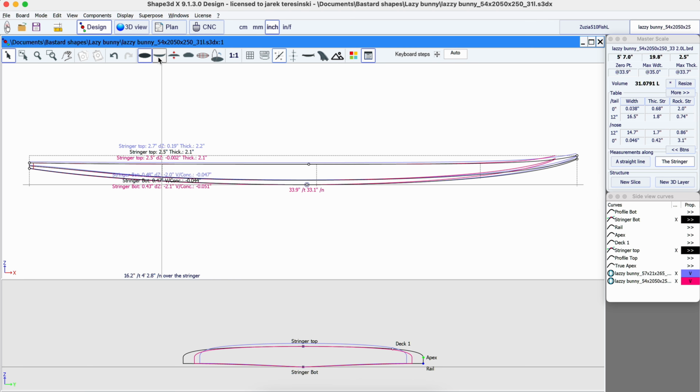Things about the rocker to consider these days. When you're designing your board, you read about the rocker, and wherever you're searching for which rocker you should design in your board, from the perspective of making the board or as a customer buying the board, we find low rocker, medium rocker, and high rocker. So what does that mean? I mean, if you're designing the board, what does that mean? What are these exact numbers? Which is the first thing, and then what is the curve of that rocker? Because a high performance board with rocker on the tip of the nose doesn't mean that just after that point you still have a high rocker.